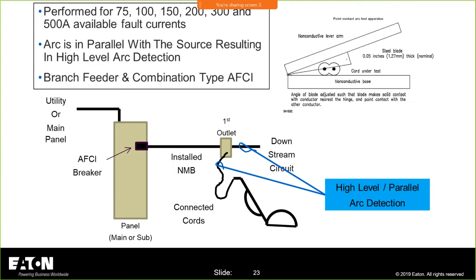NMB wire. So you think about NMB, if I did the same thing on NM wire, you have 3 conductors in NM, right? We'll have a hot, we'll have a neutral, and we have the ground. And you'll notice the placement of that ground is in between the hot and neutral. That's going to be very important when we get to understanding how we pass one of these other tests, or how we used to pass it. That's one of the standard tests.